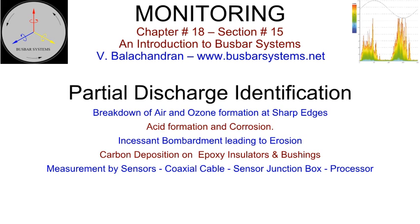It comprises sensors. Typically, an 80 picofarad capacitor is cast in epoxy, suitable for the specified rated voltage. These will block the power frequency voltage and transmit high-frequency signals. Several sensors can be placed at designated vulnerable locations in the generator connection. Coaxial cable: each sensor has a coaxial cable to transmit the signal.